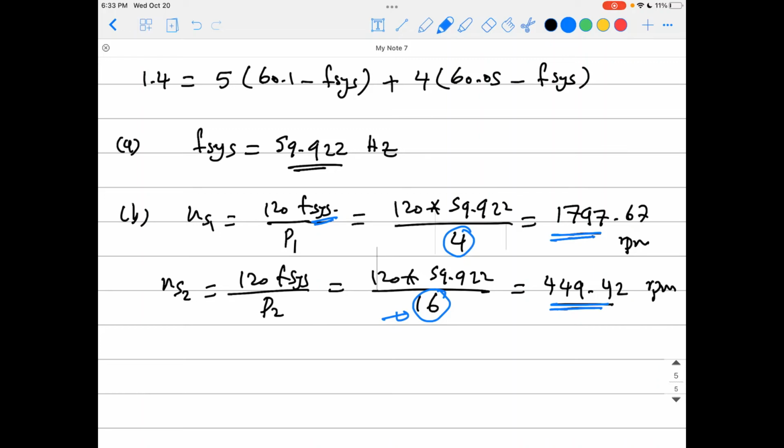While the cylindrical rotors already work at very high speeds, so the speed is just compensating for this, and you don't need as many poles. Why? Because more poles means more cost, more manufacturing complications and all that stuff. Okay, guys? So I'm hinting from the numbers, and that's why I'm telling you all the time, look at the numbers. It's engineering principles. Because you have a big difference in the number of poles, it has to be obvious that the generator with fewer poles will have a much higher speed than the other one.